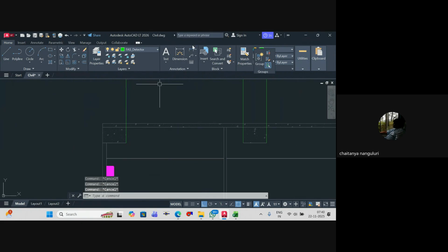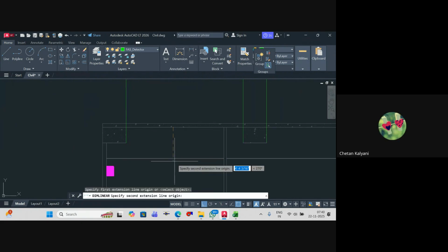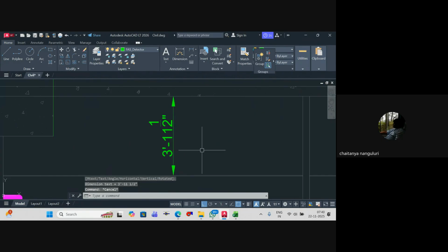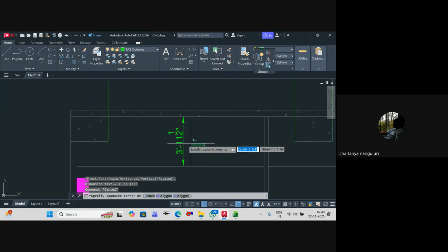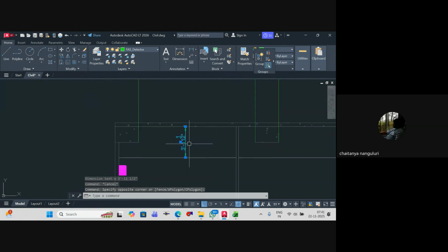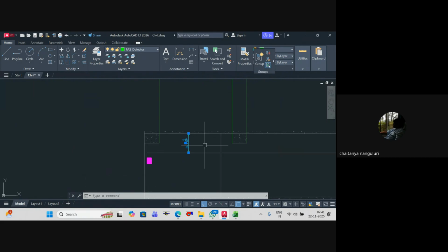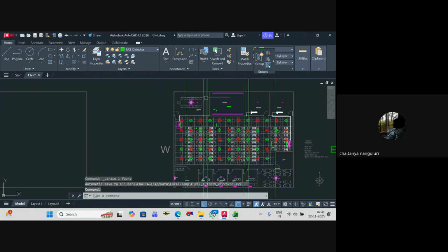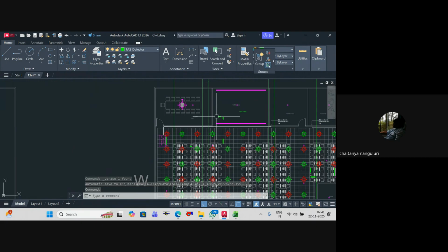First of all, let's see whether it's required or not. Only if the height is greater than 800 mm. 3 feet means it's almost 1 meter, so definitely greater than 800. So I require it above the false ceiling also. Your partitions might not touch the slab, generally. The gypsum board will be screwed only up to the false ceiling height.